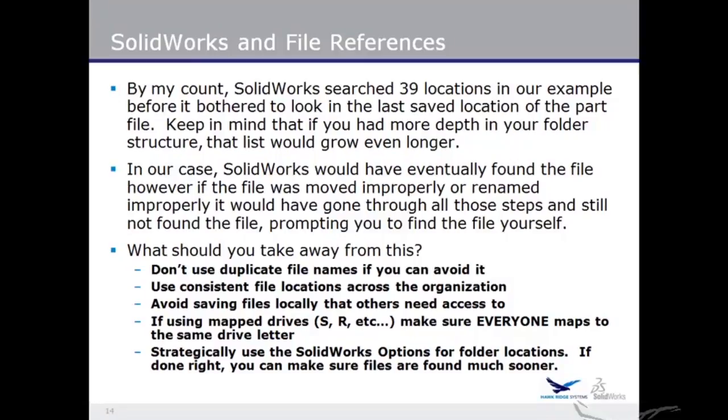If you're using mapped drives, like in my example, the S drive was a mapped drive, you need to make sure that everyone maps to the same drive letter. You wouldn't believe how many times I'll go out to organizations and I'll see somebody has it mapped to the T drive and somebody has it mapped to the G drive, and these drives don't commingle with each other in terms of the SolidWorks reference searching, so you end up with these referencing issues. So again, you can kind of see this is all about consistency.